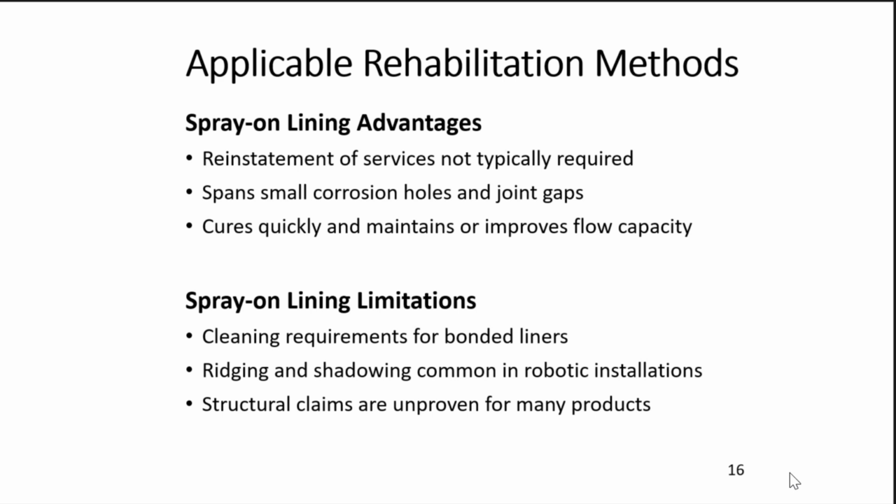Some of the potential limitations are the cleaning requirements, just to make sure you get a good adhesion. Some require adhesion, some do not, most do. There's still some tricky things that happen because most of these are done robotically. So they have a small robot that'll go in, and if you can imagine, as that robot is making its way, it tends to spray a little bit uneven. It's hard to spray a very constant thickness. So there's been quite a bit of robotic development in the U.S. specifically in this area over the last 5 years. That's maybe going to make its way up to an advantage, but still currently sitting in the limitation.